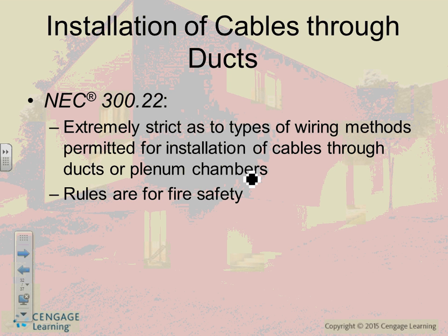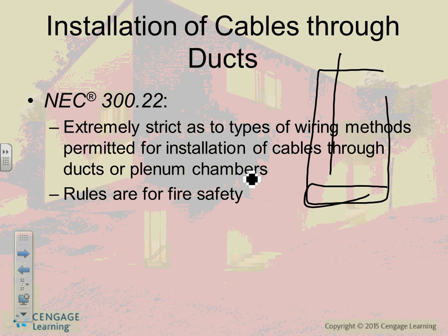Through the ducts. Now here's a heating duct. Can you install a cable through the duct that heats and cools? No, with very, very few exceptions. The only exception is that we use rigid or MC cable only to tie to equipment.